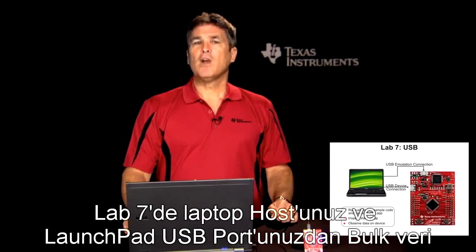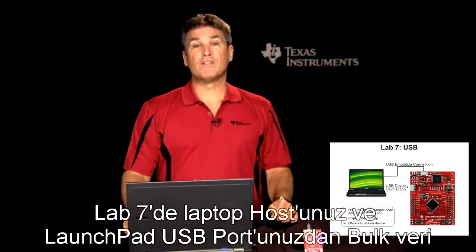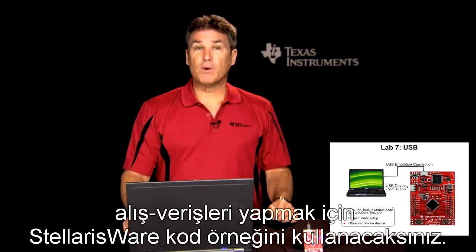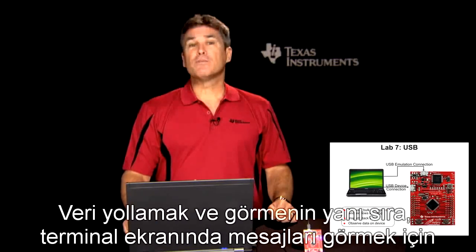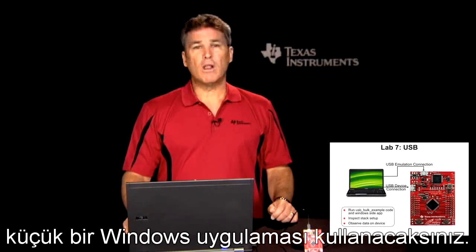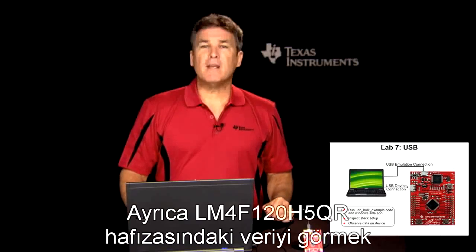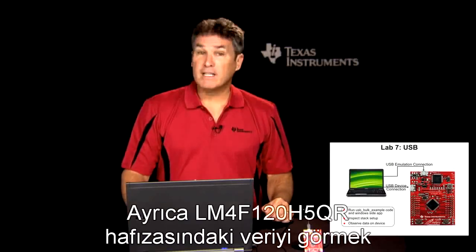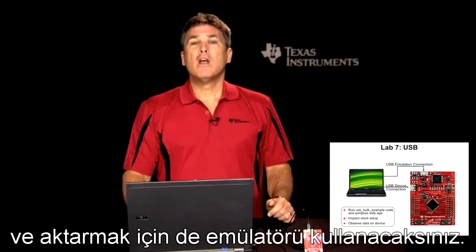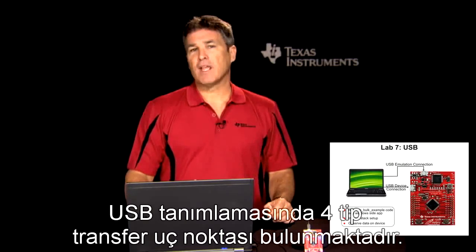In Lab 7, you'll use a StellarisWare code example to implement bulk transfers of data from your laptop host to and from the USB port on the Launchpad. You'll use a small Windows side application to send and view data while also watching messages on the terminal display. You'll also use the emulator to view transferred data in the LM4F120H5QR memory. There are 4 types of transfer endpoint types in the USB specification.